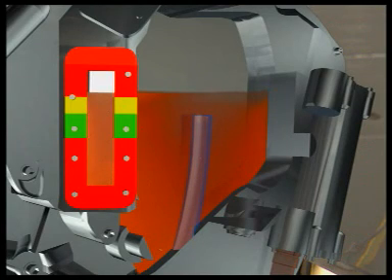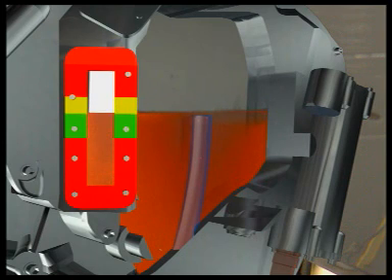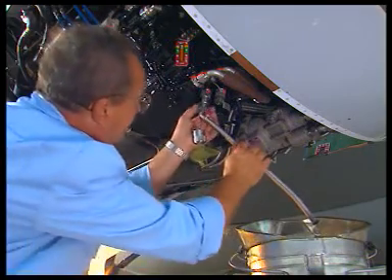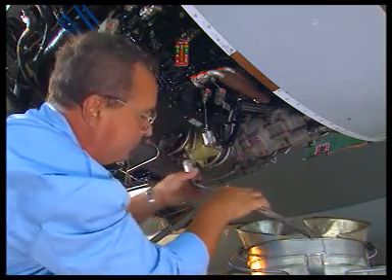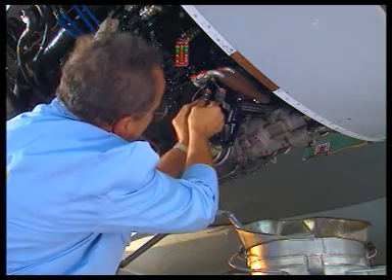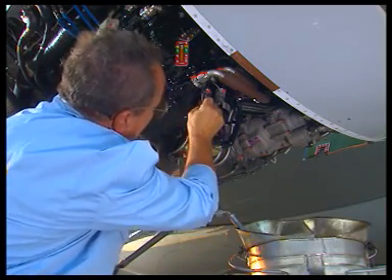Once the oil level has reached the top of the overflow standpipe, the oil stabilizes at its optimum level at the top of the green band. When only drops of oil come out of the overflow drain hose, remove it. Install the dust cap on the overflow drain port.